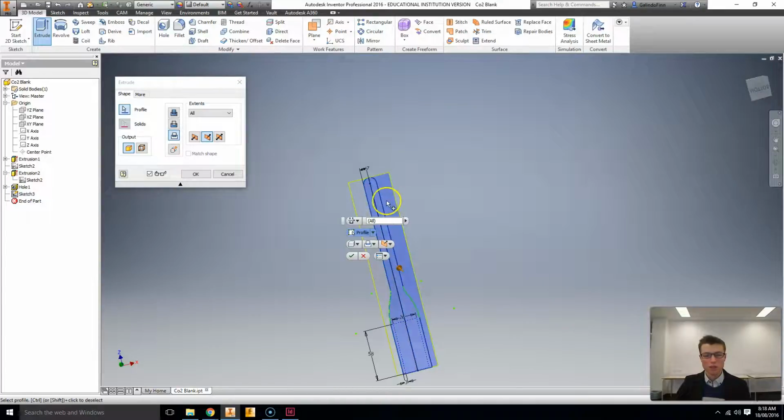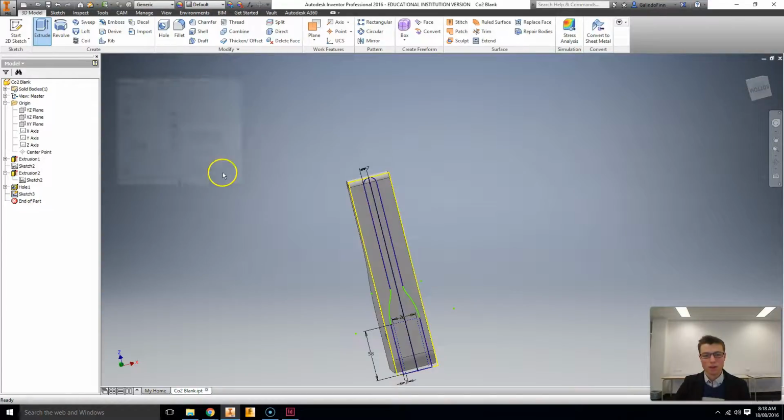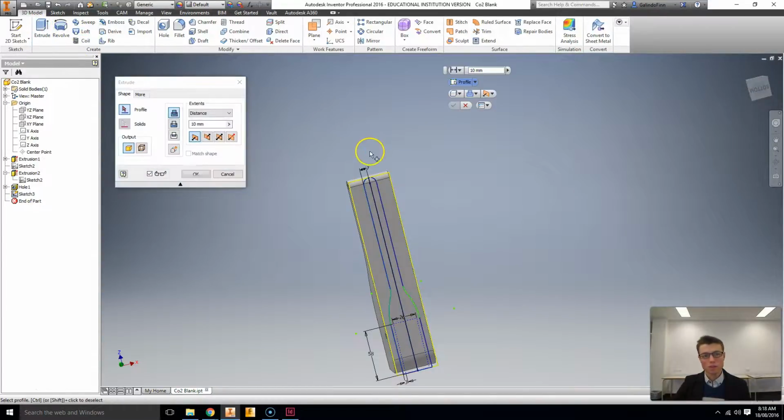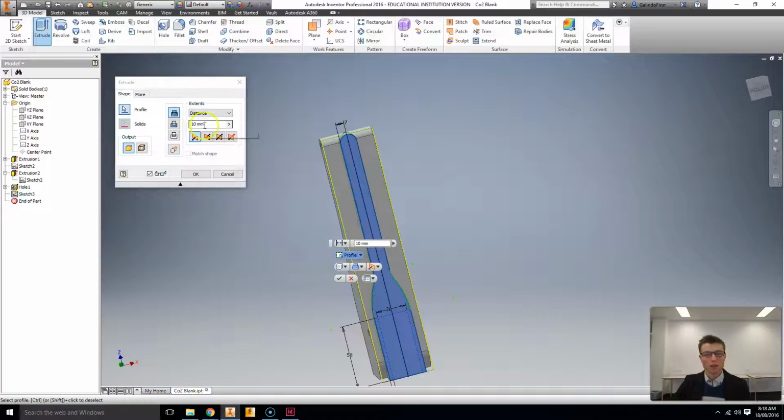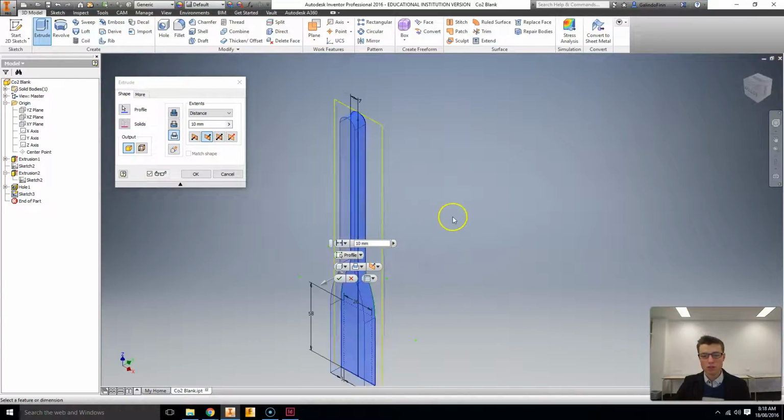Now I accidentally selected all of the halves there, so I'm going to select the little drop down button again. So I'm going to go Extrude, Profile again, select the half, and then zooming in, trying to select that other half there, but not the other one. You'll notice they sometimes highlight together. Now I'm going to click Remove Others, which is the intersect tool. Clicking one of my icons just to check what it looks like.